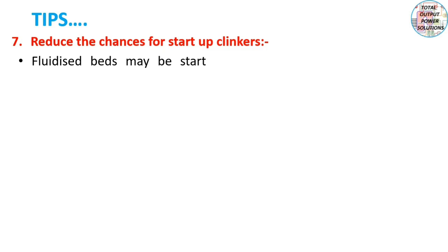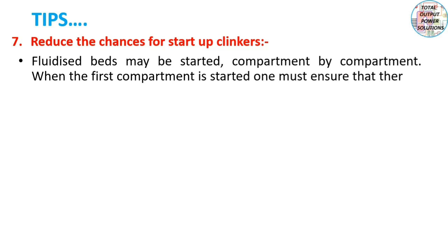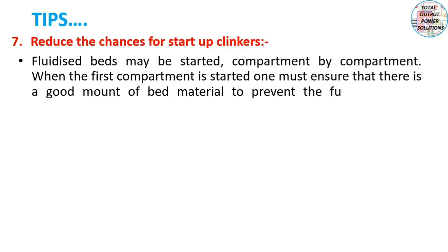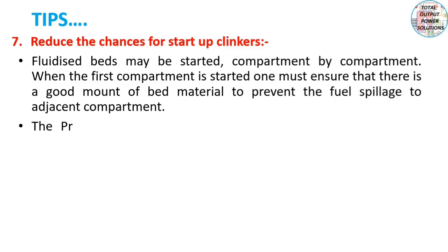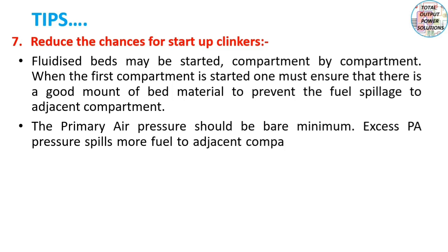Tip number 7. Reduce the chances of startup clinkers. Fluidized beds may be started compartment by compartment. When the first compartment is started, one must ensure that there is a good amount of bed material to prevent fuel spillage to the adjacent compartment. The primary air pressure should be bare minimum. Excess primary air pressure spills more fuel to the adjacent compartment.